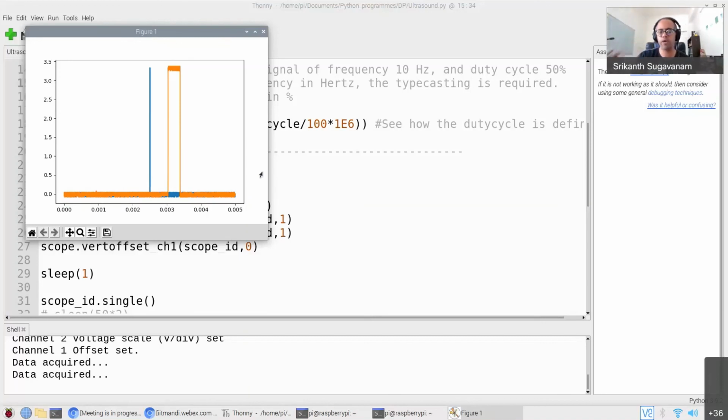If you want to work with applications where you are getting data not at regular intervals, but maybe every 1 second or 2 seconds, the timing is not going to be a big problem if the error is of the order of, say, a few milliseconds. Then you can work with the Raspberry Pi, because the Raspberry Pi offers you the advantage of doing a lot of analysis. Then you also have the analog to digital part. You have to think about it. So these are essentially the pros and cons of using an Arduino and a Raspberry Pi.